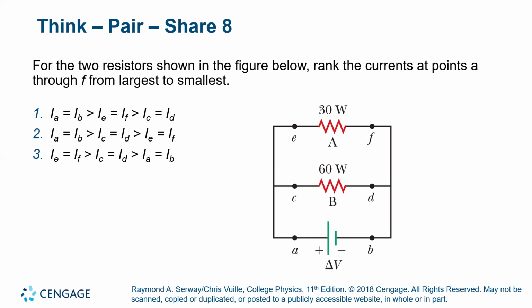So in this situation, we have the voltage source connected to nodes C and E. And what you're going to do is track the entry points of the current and the exit points of the current going through the elements.